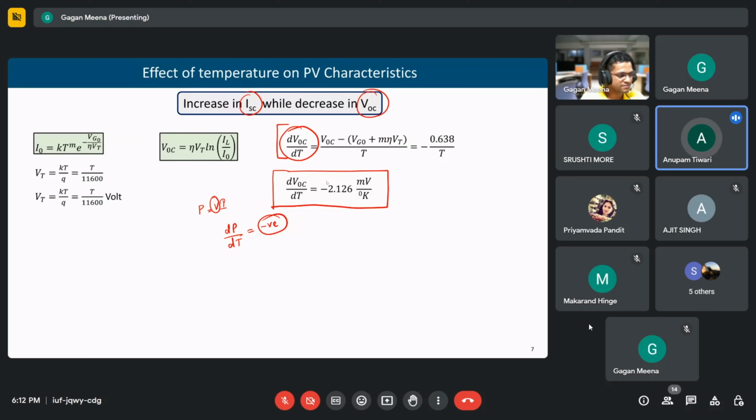That is why the floating solar cells are there for the compensation of temperature. Correct. So that is one advantage of having floating solar panels, because they will help in cooling. The temperature will not be that much because water is there below, so it will always help in cooling. It will create a cooling effect, and especially at higher altitude, the cooling effect will be much more significant.